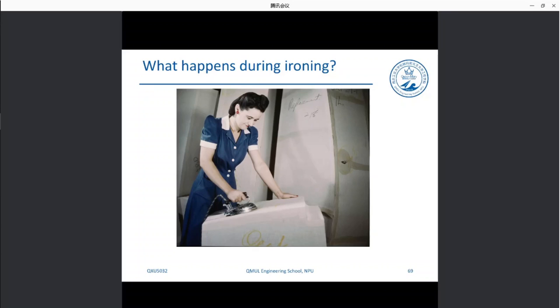What we do essentially is we provide them enough energy in order to soften our material, and with the force, we give them a specific conformation. And because we give them a specific conformation, we straighten out our materials by using thermal energy passing through the glass transition temperature, and force. So a combination of the three provides a very straight piece of clothing.